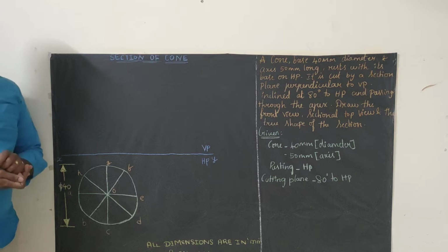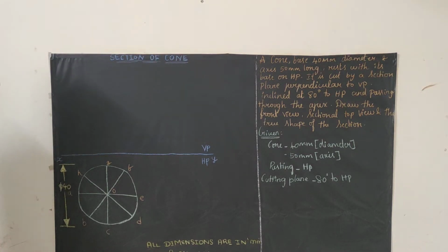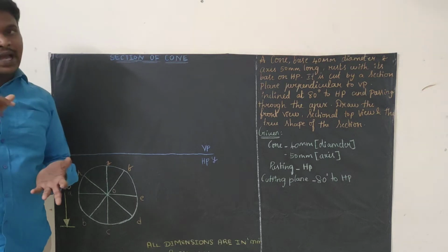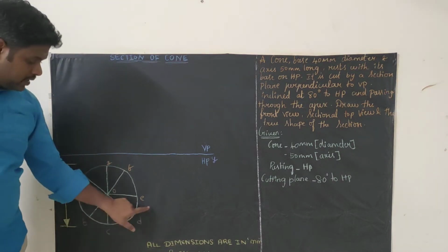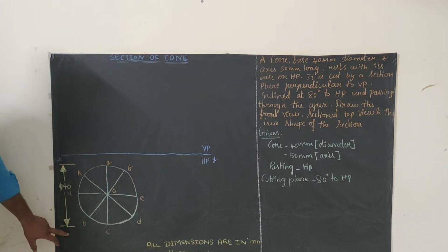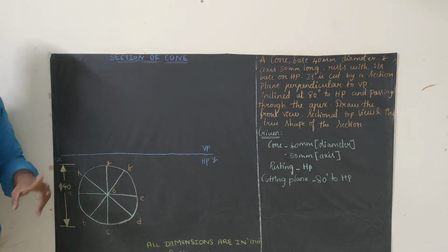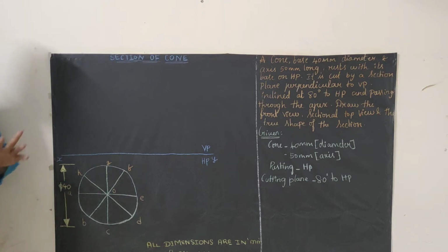After that, naming we know very well. For a cone we will have only 8 namings. In case of a cylinder only we will have 16 namings, and the topmost portion will be the apex. So you have to name them A, B, C, D, E, F, G, H, and then dimensioning. These are the extension lines. They should be drawn with your 2H pencil. These lines are called dimension lines. They should be drawn with your H pencil, and the arrowhead and 40 should be written with your HB pencil. So this is the way we need to dimension it.